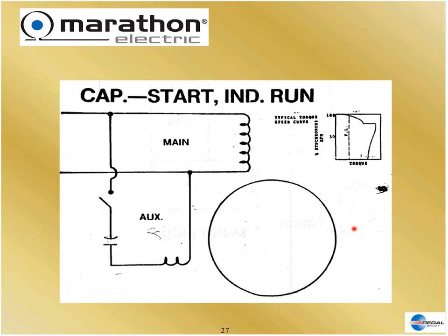What's the capacitor? That's the dial on the radio. It's a variable value capacitor. You turn the dial, change the value of the capacitance until it negates this inductance at the correct frequency, and that radio station plays in your speakers. So all we're doing here is tuning our radio for 60 hertz because that's the frequency we have.